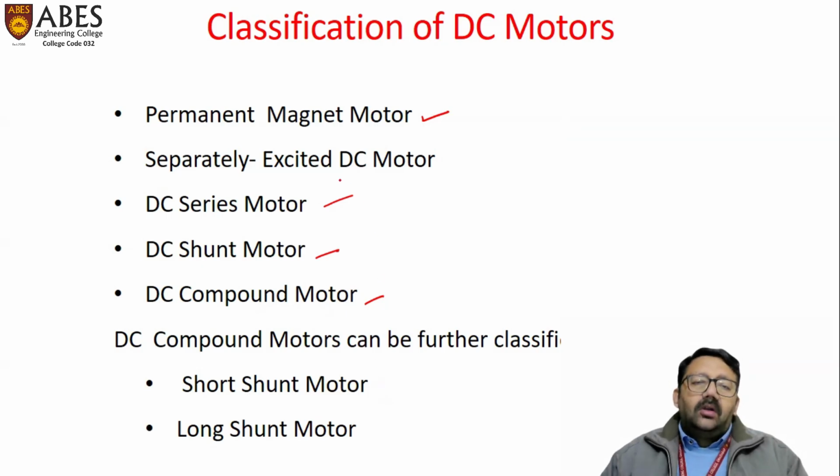First of all, we will discuss the permanent magnet motor. As the name suggests, in these motors, for developing working flux, pieces of permanent magnets are placed around the armature. These motors are very compact in size, but due to low power output and constant magnetic field, as flux is developed by permanent magnets, we cannot change motor flux.